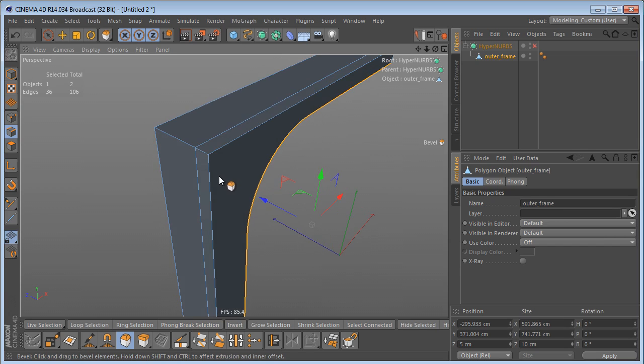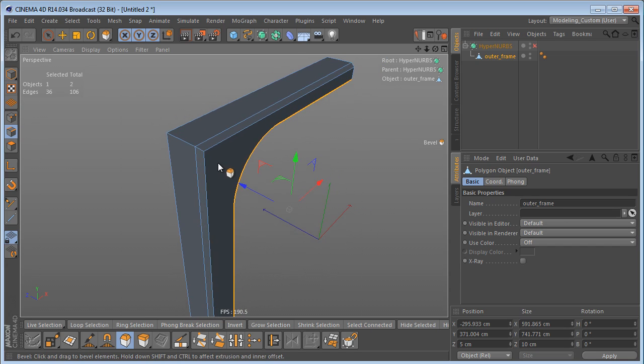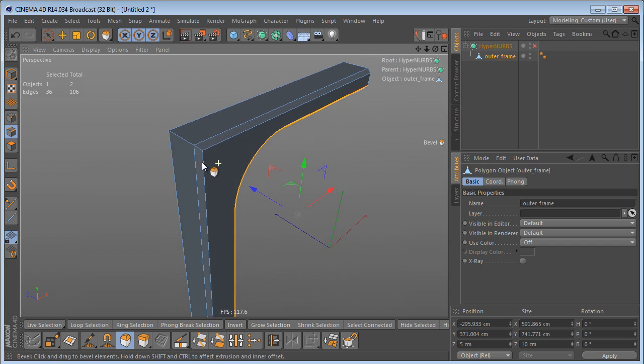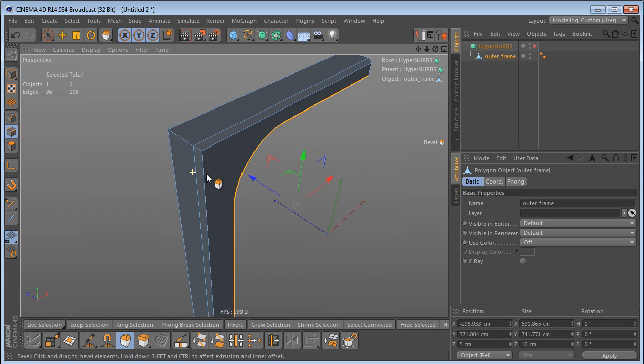Chances are by doing that you'll also change the basic shape of the object, and you don't want that to happen. That can be difficult and time consuming to fix depending on how complex your model is. So I prefer to use edge cut or loop cuts or the knife tool, basically anything except for the bevel tool.